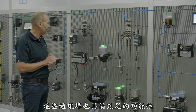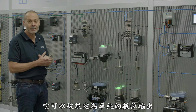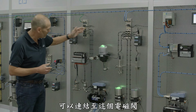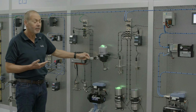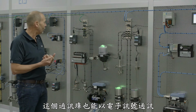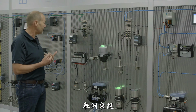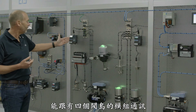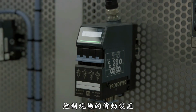These ports are also quite functionally capable in the fact that they can be set up as just a digital output. In other words, this first port could be used and is connected here just to a solenoid valve in 24 volts DC. So in other words, it's operating just as a traditional I/O block. However, the ports can also talk digital communications to the devices in the field. So as an example, a similar IOLink port in this instance is talking to a block that has 4 valves in there controlling actuators in the field.